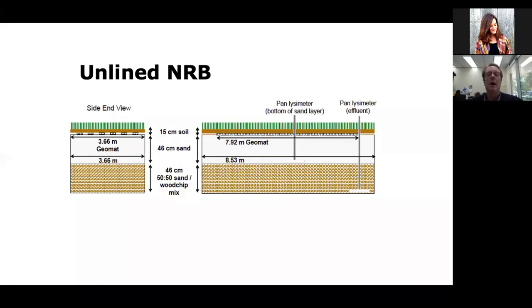Suffolk County, as any regulator would, requires that there's some soil underneath systems, and for drain fields, they require 2 feet of soil. So if we have about 1.5 feet of topsoil, 1.5 feet of sand, and 1.5 feet of sand and wood chips, that's about 4.5. Let's err on the side of caution, call it 5 feet. And then we need 2 feet above any potential groundwater. So these systems would work with depth to groundwater of 6.5 to 7 or above. They would be fine.